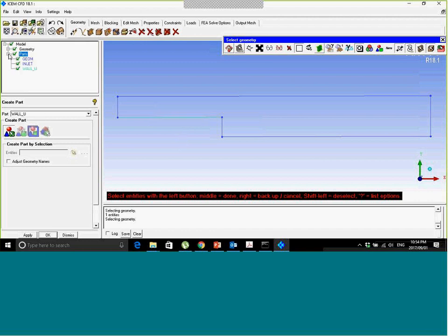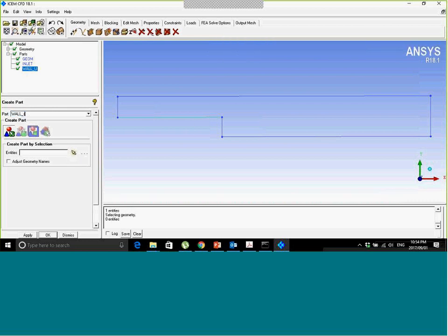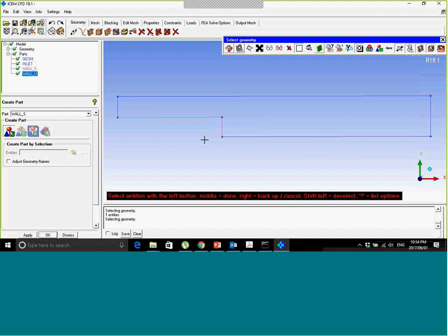If you click on the plus sign, you can see the parts over here. U. Then we have S. Let's select this boundary, and we have wall down, wall D, and then we have the wall upper, and we have the outlet. You can call this one out. So the name does not make any difference. It should be a name that is clear to you, that you can understand.